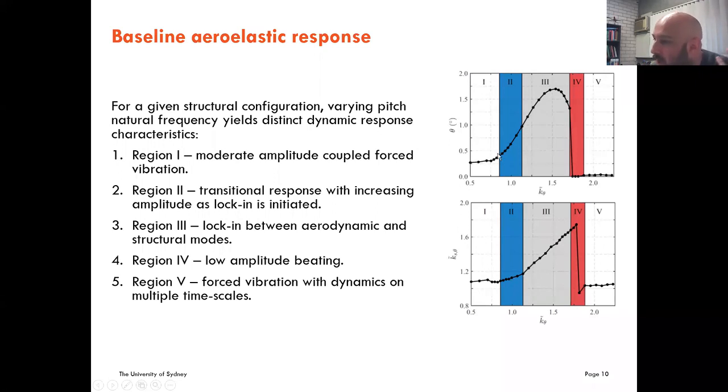So we start getting an increase in amplitude. You could almost think of it as a resonance, but this is not a resonant type of behavior in the common sense that we would know as resonance. And as we go into region 3, we get a complete lock-in of the behavior. Then as we start moving away, there is a shift and a changing phase, and then we go back to very low scale oscillations of our aerofoil.